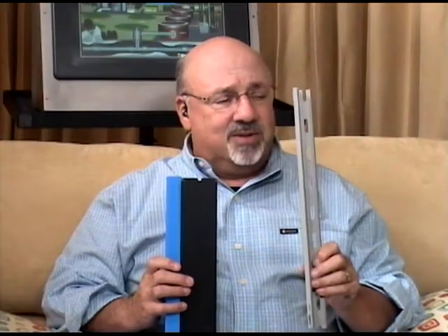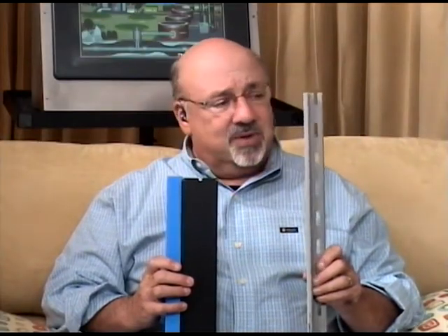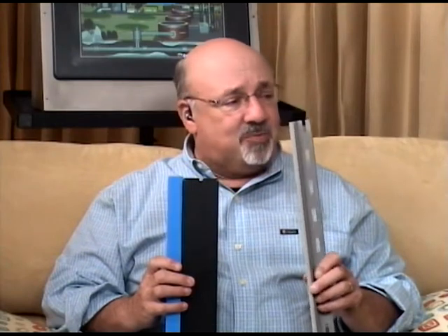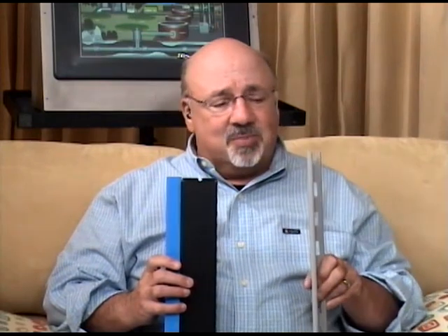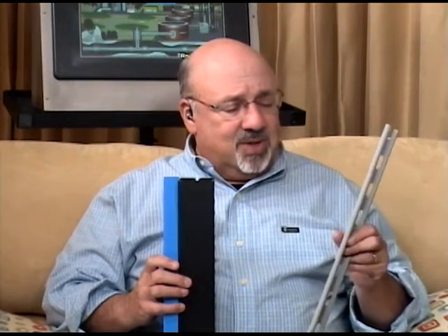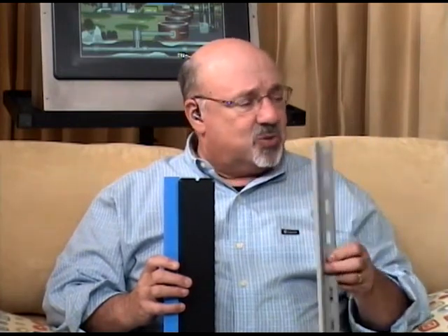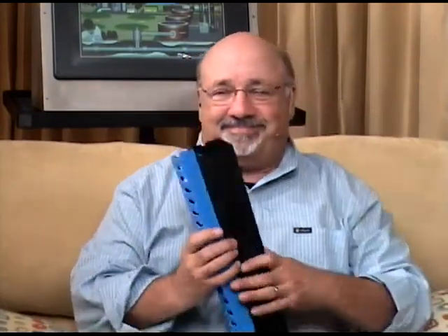One of the accessories I'm holding in my hand here is a divider. This is pretty clever. You're setting up your wire duct, and you have a 4-inch piece of wire duct. You have different signals like low voltage and high voltage, or you're trying to separate maybe input I/O wiring from output wiring. You can stick a piece of a divider down the middle to help separate this, and this is set up so you can clip on different accessories to help hold the wires in place while you're wiring. And our last product of today is going to be our DIN rail.